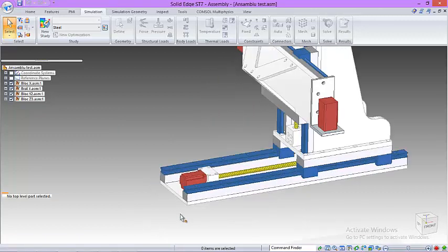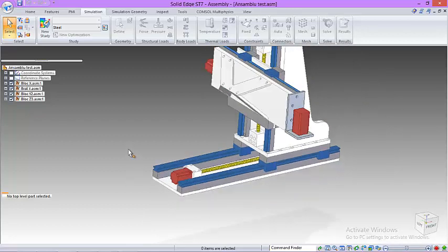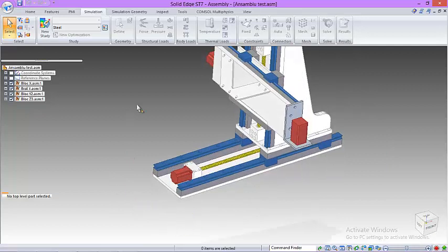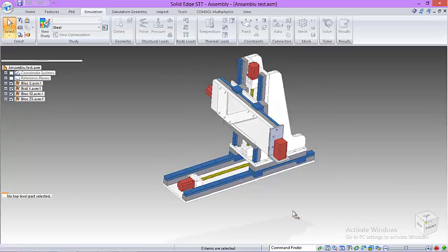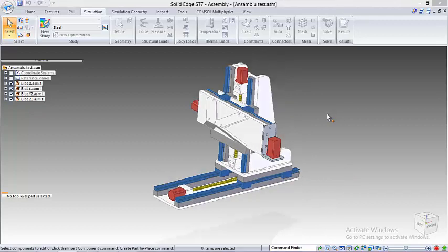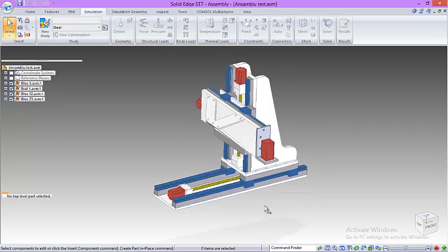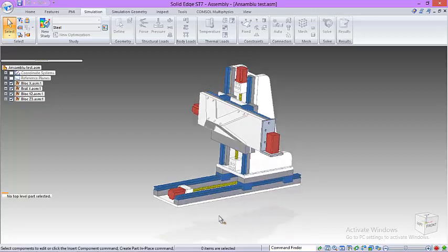As we go through the components, I'm going to explain the color code. White is for aluminium, gray is for cast iron, red is for the electrical stepper engines and servo motors, yellow is for the spherical profiled thread, and blue is for the linear bearings. Now, aluminium serves as fixed mounting position for the other elements of the assembly. The cast iron is supposed to take some of the structural load from the linear bearings, and it's also supposed to prevent small bendings and twists that happen over time, normally in metal.